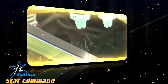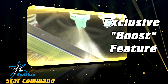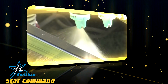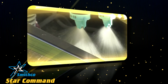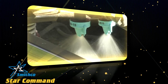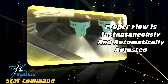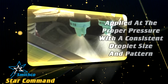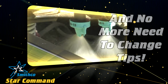Sharpshooter achieves the entire rate range by utilization of an exclusive boost feature. This feature uses 2 tips mounted on a pair of nozzle bodies spaced 20 inches apart. Sharpshooter has the unique and innovative ability to coordinate flow through one or both tips to attain the desired rate while maintaining a constant pressure and droplet size. The net effect? Proper flow is instantaneously and automatically adjusted to respond to the range of rates and speeds required by the application. Quality is maintained by virtue of the proper rate applied at the proper pressure with a consistent droplet size and pattern, and no more need to change tips.